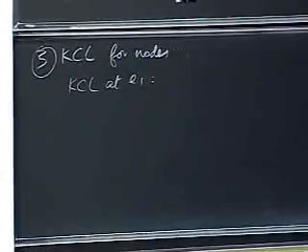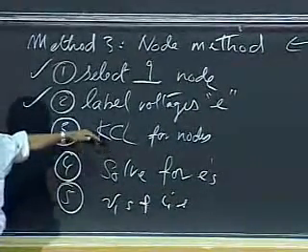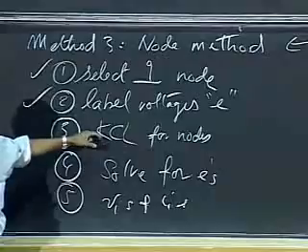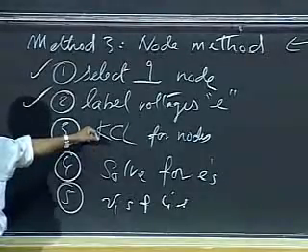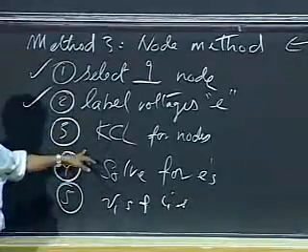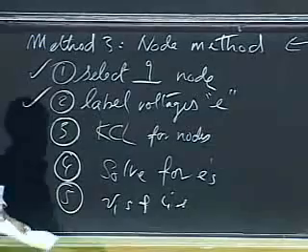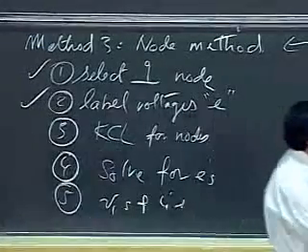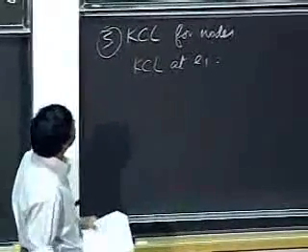So the trick that I adopt is that to write KCL, I use the node voltages and implicitly substitute for the node voltages, divide by the elemental resistance, for instance. So take the node voltages and divide by the resistance, get the current. Okay, so I implicitly apply element relationships to get the node currents. So the example will make it clear.